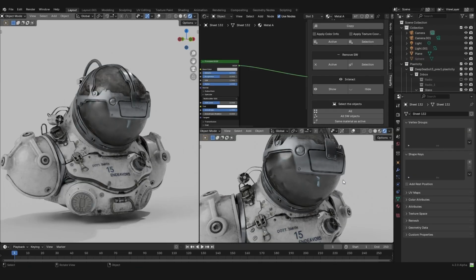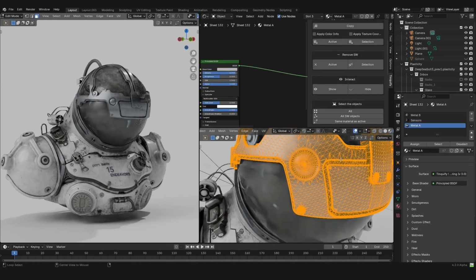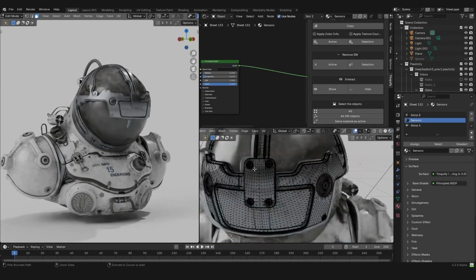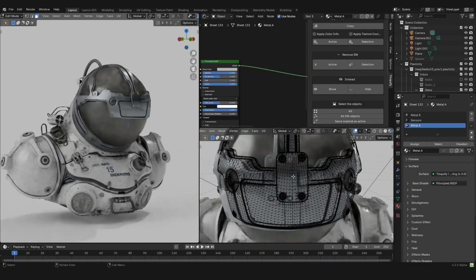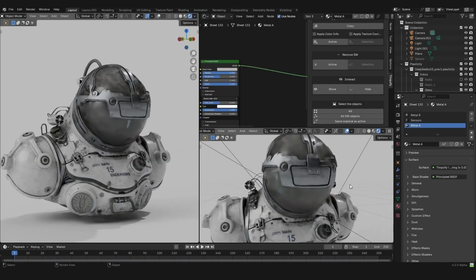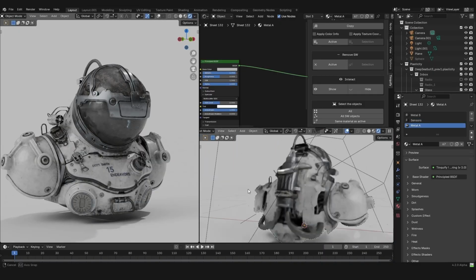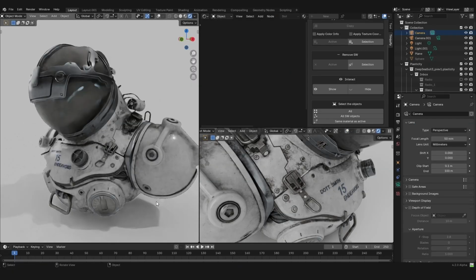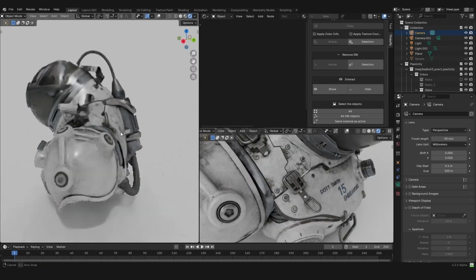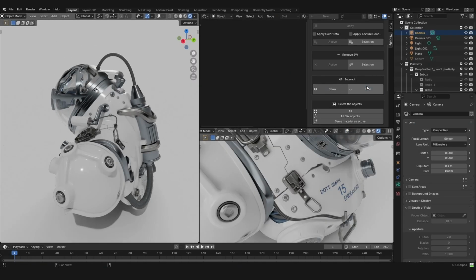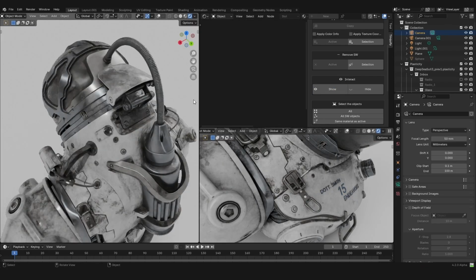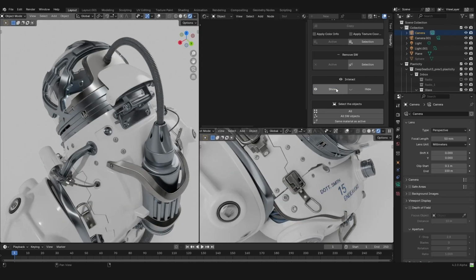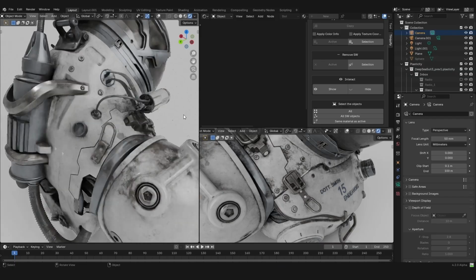So you can have an incredibly smooth workflow between the modeling and texturing phase with this method. One thing to mention is that it is advised, however, to start this process of texturing once you have at least some rough shapes. If you don't do that, then the only thing you will need to do is just reassign the material because you have created a new piece when you did a boolean or when you retouched some surfaces, but not a big deal at all.